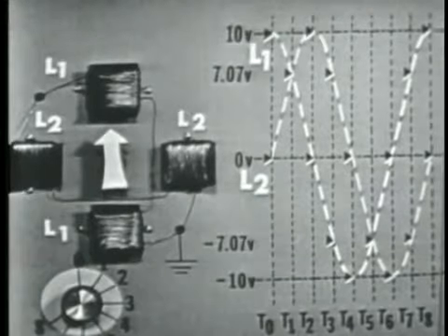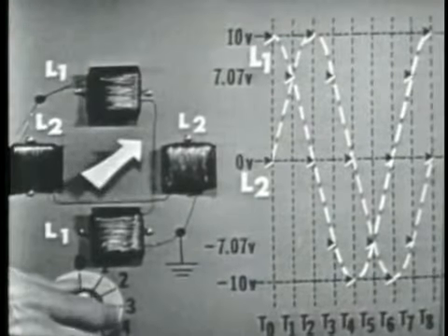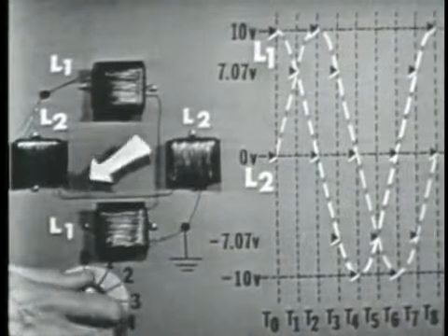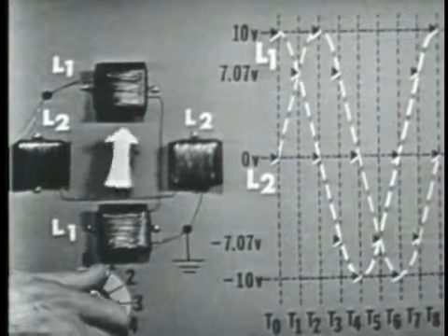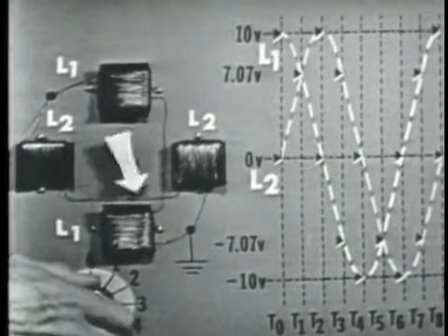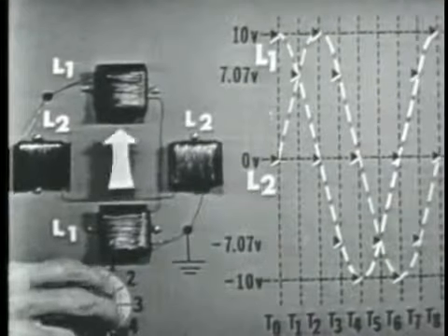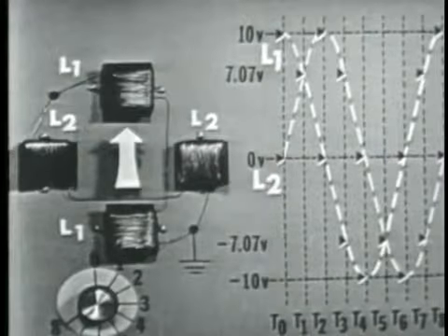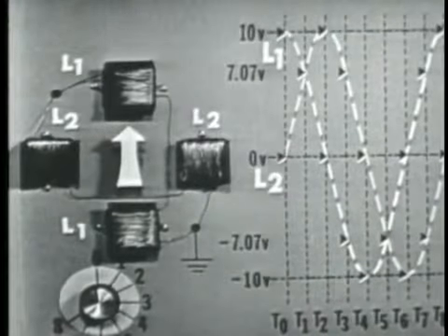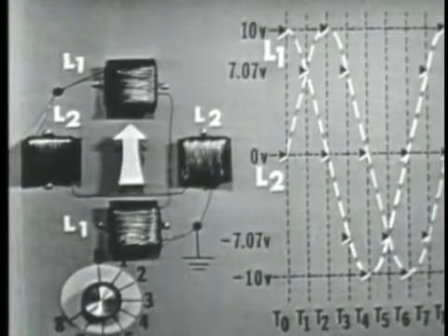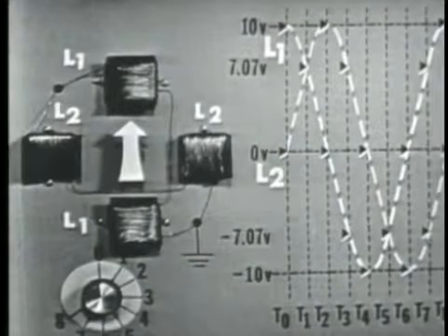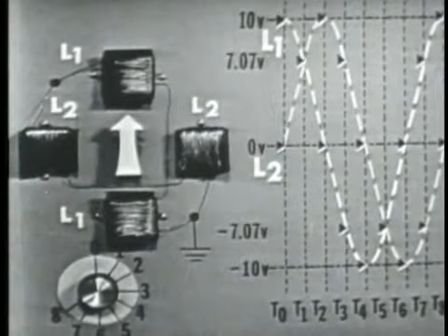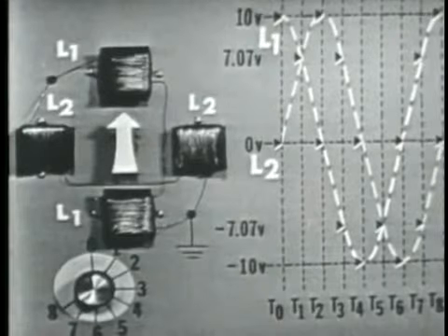Item 7 shows you how one complete revolution of the magnetic field is accomplished by applying these out-of-phase voltages to the stator windings. Now, you can study this very, very carefully so as to fix the principle in your mind. And, by the way, we might point out, Tom, once again, that you can apply the left-hand rule to all these coils and prove precisely what we've said, right? We can develop a rotating magnetic field. I'm certainly glad you said that, a rotating magnetic field that induces a voltage in the rotor, causing it to become an electromagnet, which will follow the rotating magnetic field.